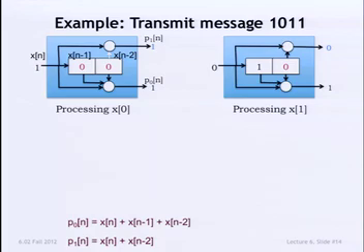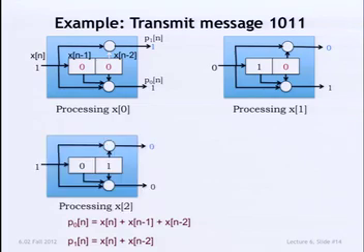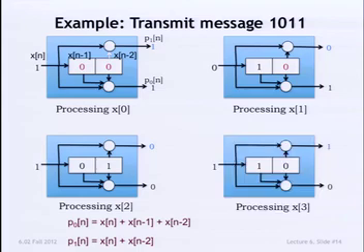Okay. In fact, the word convolve means to fold together, and this is what it's actually trying to capture. You're folding together these 2 sets of weights, the weights on the taps here and the input sequence weight. And then the next 2 cases similarly. Okay, and that's what gets sent out at the bottom.